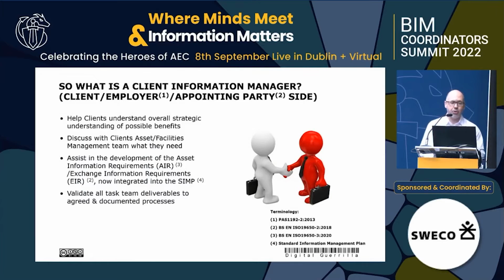So what does a client information manager do? We're basically there to help the client understand the overall strategic benefits and what's actually possible, discuss with the client's asset management team what they need to deliver, assist in the development of their AIR, their asset requirements, their exchange requirements, or what we now call the SIMP, the Standard Information Management Plan, and then finally validate all the task team deliverables when they're handed over at each stage of the project. So it's not just a case of helping the client specify the standard, but when the delivery team start to deliver it, we're also validating what they hand over to make sure it meets those requirements.